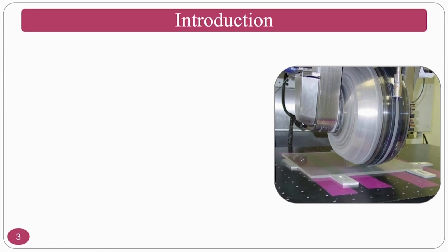So, introduction to the MRF process. See, this is how the MRF process works. This is the workpiece and this is a tool where the fluid is dispensed, and because of the magnetic field that is there inside the grinding wheel, it becomes a thin ribbon type of structure, and this is called a flexible polishing belt, or you can say flexible polishing ribbon. It is so thin that many people call it a thin ribbon.